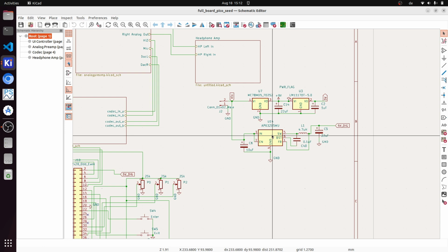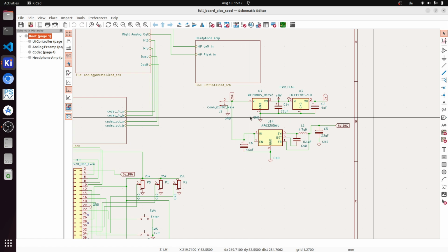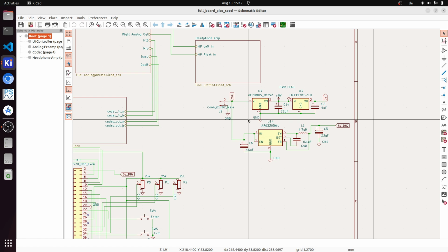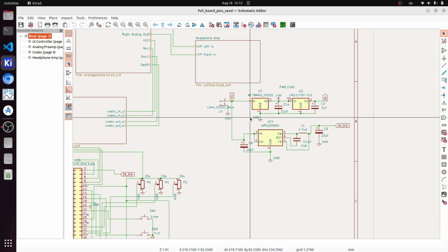This is then converted through a half-wave rectifier into plus and minus 12 volts, which I thought was a good idea, since I was used to working with plus minus 12 volts when building my analog modular synthesizer, but it has proven that this wasn't really a good idea for this device, because there was still hum inside, and I needed to add really big capacitors to get rid of the noise somehow, but it still remains in some settings.